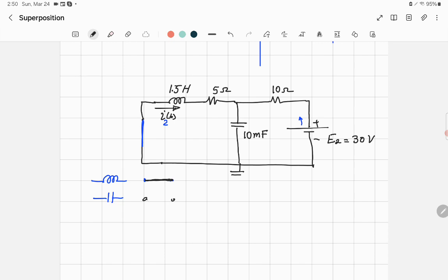The capacitor behaves like an open circuit. So what do you mean by that? It means I'm going to remove this inductor and put a short circuit, and I'm going to remove the capacitor. Nothing. It's an open circuit. So now that's your circuit when you have DC.